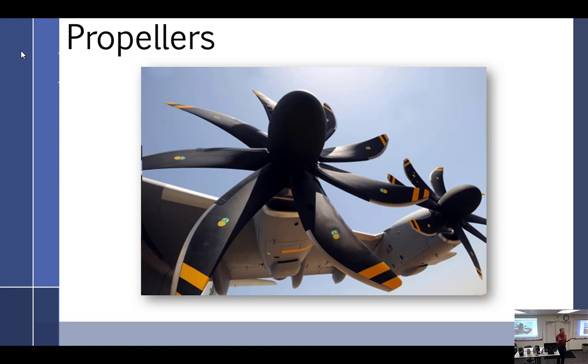We already talked about what you have with a fixed pitch propeller at 1,000 feet, where you're at 65 or 70% horsepower, versus 75% power at 10,000 feet, where it's wide open. So up there your RPM is much higher to get the horsepower than down here. You've got to find one spot that works for everything, and it just doesn't work. So propellers tend to be problematic in that way, and we're going to look at that.